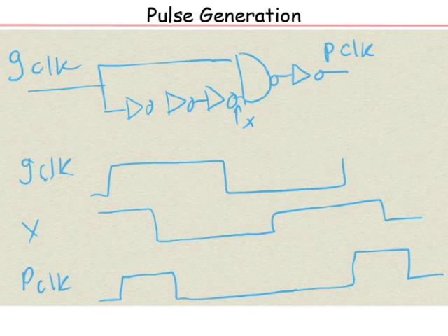I'm saying if you look at the flop as a black box, inside you might have buffers and so on and extra delay. So that can cause, with respect to the arrival time of the signals at the boundary of the flop or the latch, the relative hold time and setup time to be shifted left or right based on internal delays in the data path and the clock path.